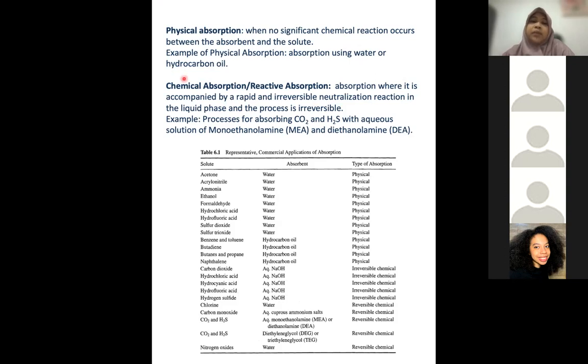Okay, but chemical absorption or reactive absorption is actually the absorption accompanied by a rapid and irreversible neutralization reaction in the liquid phase, and the process is irreversible. For example, the process for absorbing CO2 and H2S from aqueous solutions of MEA, monoethanolamine, for example.